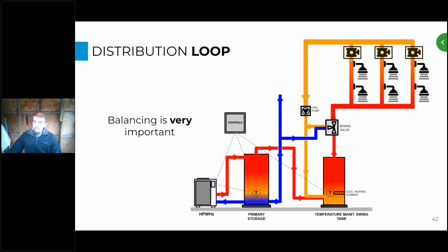And there's a couple different strategies for balancing valves. The most common I've seen are these manual circuit setter valves. And the downside to those is a plumber has to manually adjust every branch loop with these valves. And sometimes you might have 20 branches, right? And then once you adjust, say you adjust the first 3 branches and get the flow perfect, as soon as you start shutting down the farther loops and increasing the pressure drop there, now the flow actually changes in these first loops. So you have to reiterate and readjust all those valves again until everything's within spec. So that's not super realistic from what we see in the field.